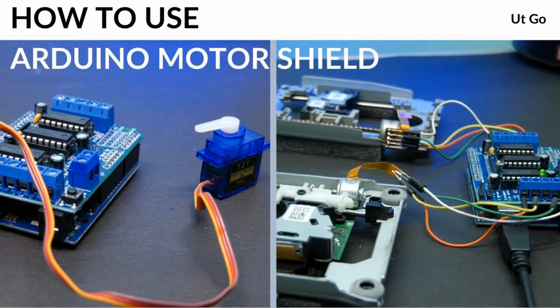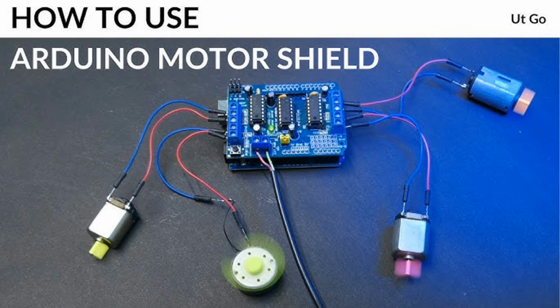Here's an overview of BLDC motor drivers. 1. Basic BLDC motor drivers. Function. Basic BLDC motor drivers provide the essential functionality to drive a BLDC motor, typically using a 6-step commutation process, which involves controlling 3 phases of the motor in a specific sequence. Operation. These drivers switch the power supply to the motor's windings using MOSFETs or IGBTs. The driver uses a predefined sequence, usually 120 degrees apart, to energize the windings, which generates a rotating magnetic field that causes the rotor to spin.